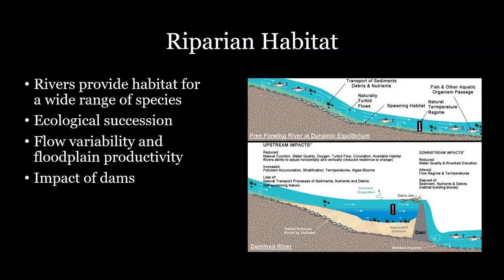That all gets complicated by the fact that we have dams a lot of times on rivers. And so these dams impound the water flowing down the river and can have a number of impactful side effects besides their impact on flood control. One of them is that when you have that water sitting around in that upper basin for so long, it's exposed to more sunlight, and therefore it increases the temperature of the water. And as we talked about before, high temperatures are kind of like a pollutant and can decrease productivity of different species. Additionally, all the pollutants that come washing into the river get consolidated into this basin, and you can have algal blooms and pollution accumulation that results.